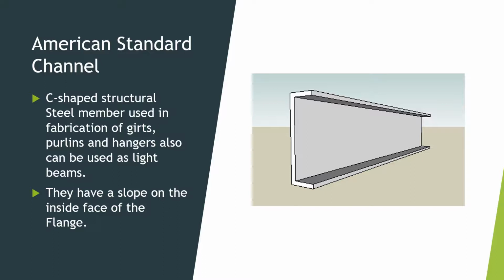The purlins, on the other hand, they're found in the roof, and that's where decking is connected to. These will hold the roof section, so if you let the channel sit and connect as it looks in the picture, right there, guys, in front of you, that will resemble a purlin as it sits on a roof. That can also come, besides a C, it can also come in a Z shape, and I'll show you a little further into this course what that looks like.